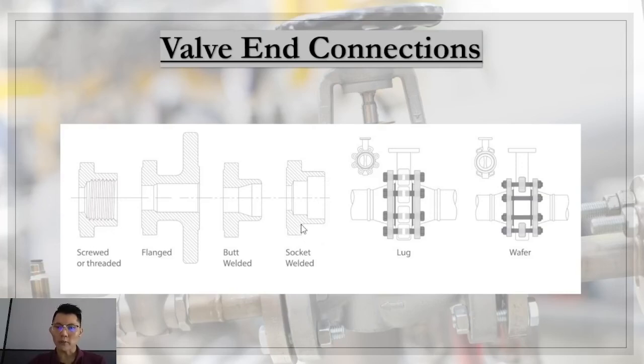For the butterfly valve, we have two types as well. This one on the second right is a lug type. You can see there are ears or lugs in this. This is a lug type, and this one is a wafer. The wafer will be lighter, because in construction, it is actually lighter. So the selection depends on the application and your requirement as well.